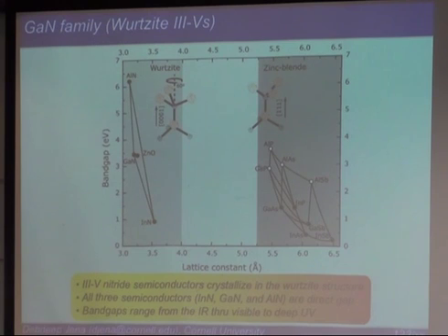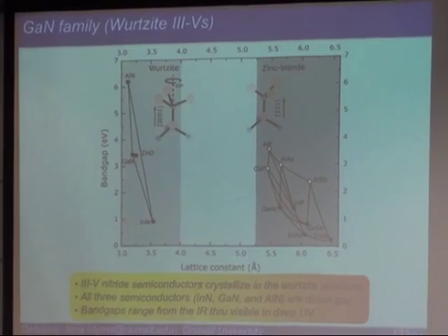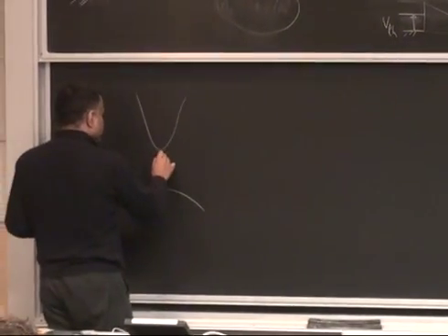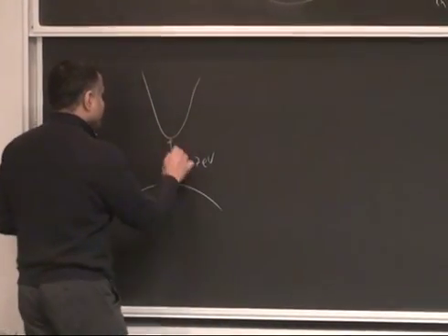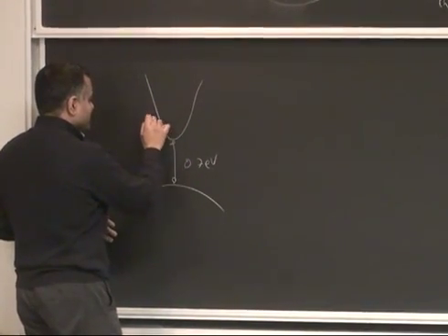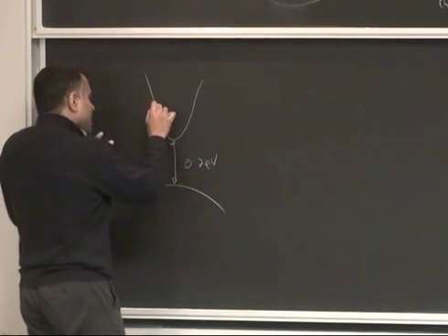So that happened almost simultaneously, one at the Ioffe Institute in Russia, and the second here in Phillips Hall by Bill Schaff. And when they did the measurement, they measured about 0.7 eV. The reason people were measuring these very large band gaps is that the material was so defective earlier. So the real band gap is about 0.7 eV, the best we know today.